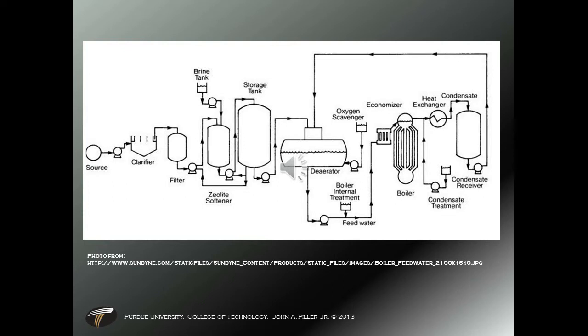It would have other chemical cleaning of what's needed of that water. We need the purest water we can get to go into our system. This water, feed water, is probably cleaner than anything you'd ever drink. The issue with dirty water is that it would bring in corrosion to all the small tubes in the boiler, corrosion to the turbine blades, and that causes mechanical failure and issues along the line. We need to reduce the amount of maintenance required.